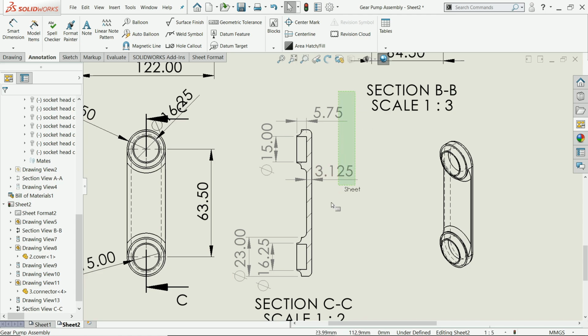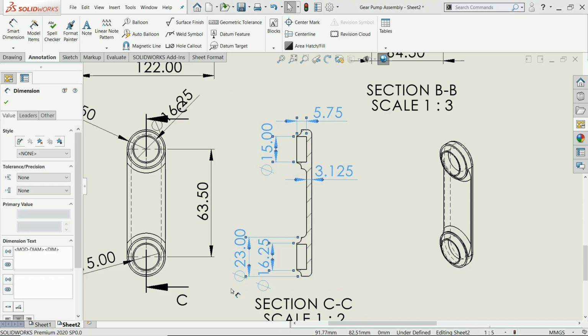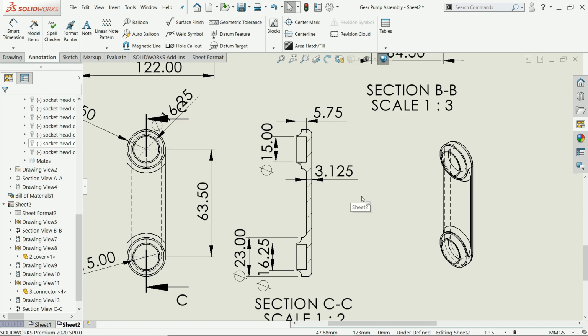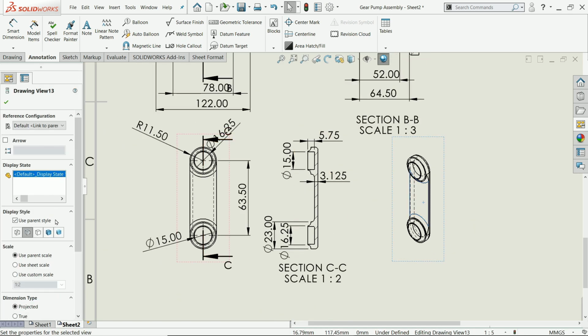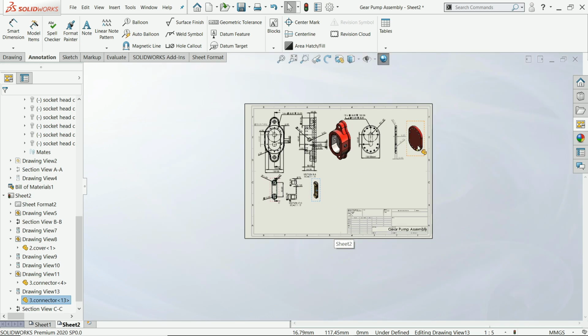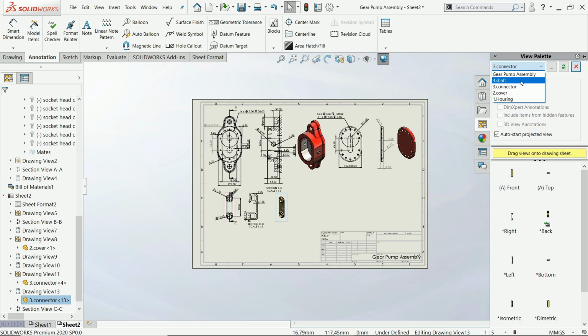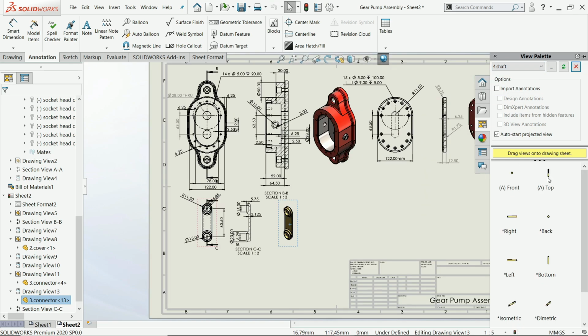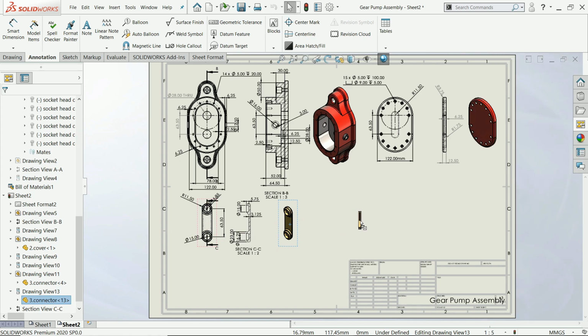Now see, this whole drawing seems gray. So click, go to other, and here one option, layer. Click format, say OK. Now everything becomes dark. This one, click shaded view, keep high quality so it looks sharper. Okay. Now this one is finished. So let's try the shaft. Top view. I'll keep it here.